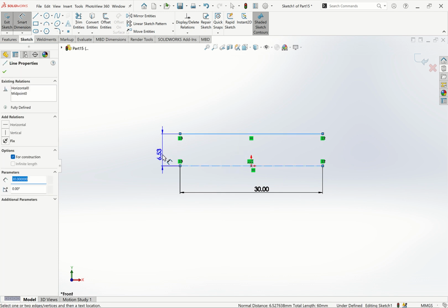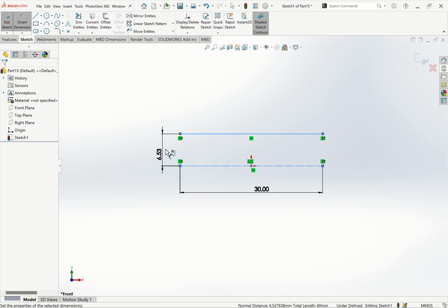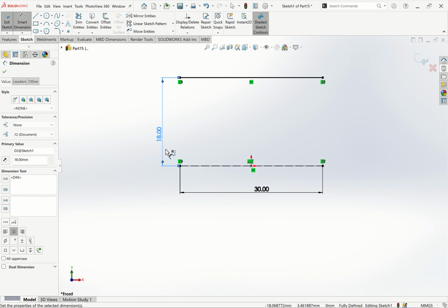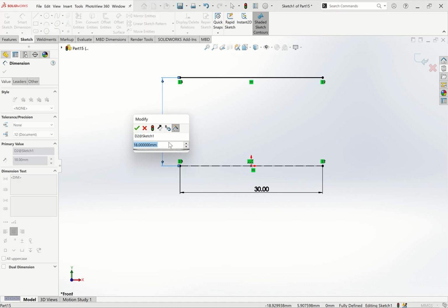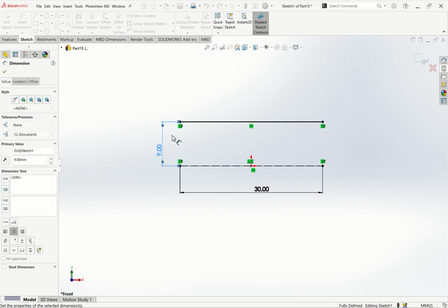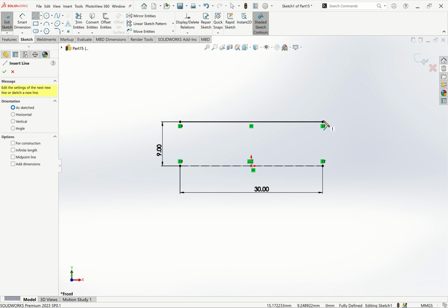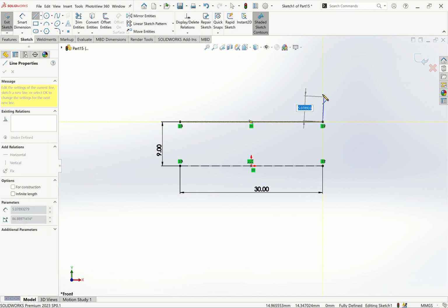I want to do a revolve. So I have M20x2, which means my pitch is 2 and my major diameter is 20. For external, we're using a major diameter of 20. For internal, I will use the minor diameter as 20 minus 2. But remember, I'm doing it revolving, so I'll divide by 2 again. So you take the major diameter minus the pitch. So this is what we obtain for our internal.